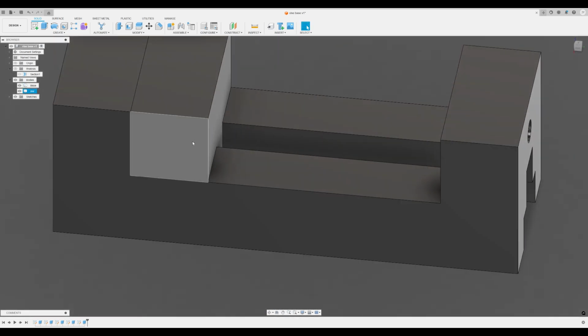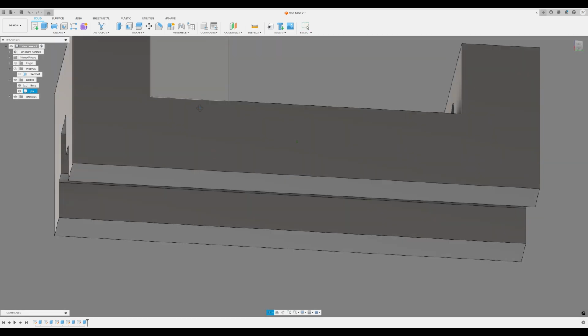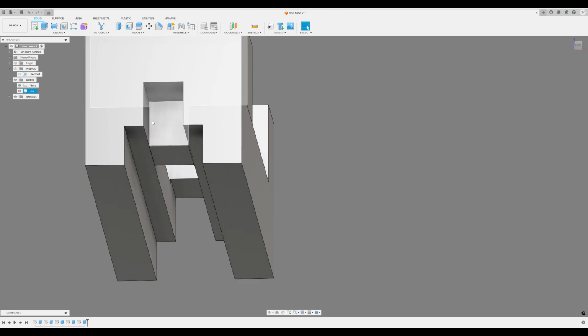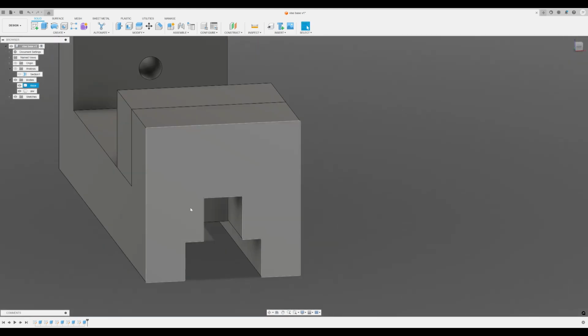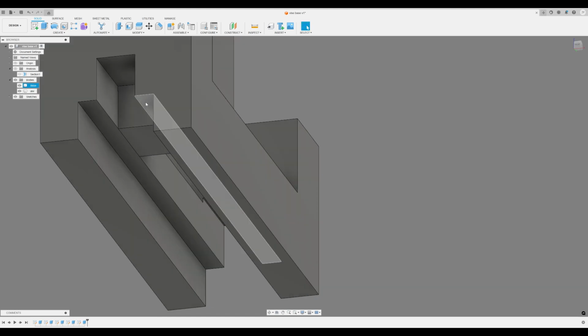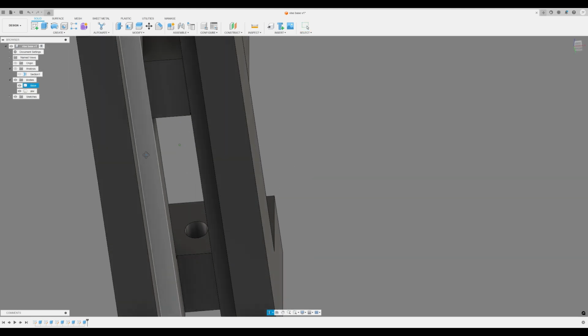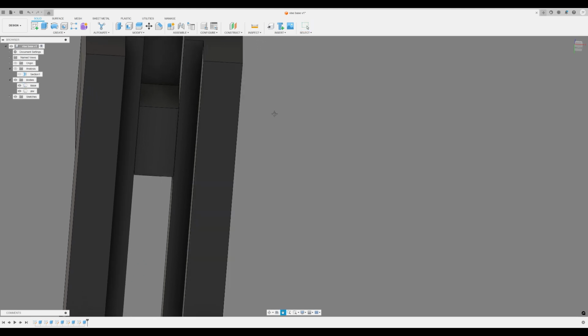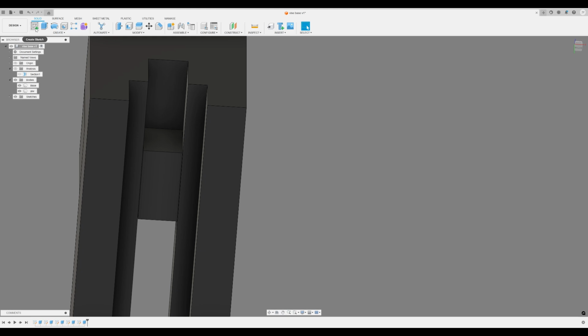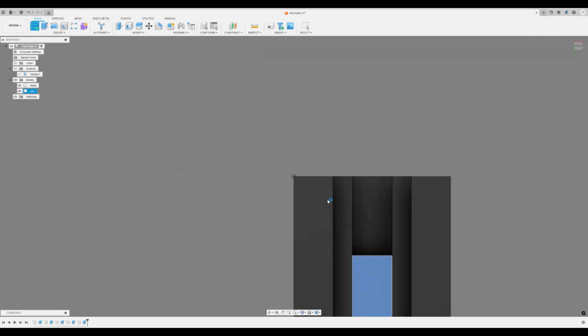The only problem now is it can lift directly up, out. So we need to capture that inside. So this groove right here keeps the twisting moment down. And now this groove right here, we can add a plate to keep the bending or the dropping movement, or movement along the Z axis, out. So I'm going to create another sketch, select this face,